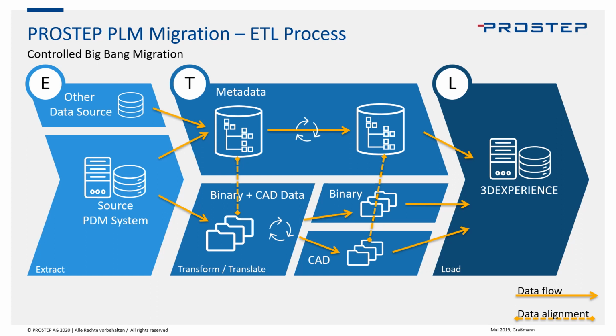Generally, CAD data with the PLM, when it's opened up, does some introspection, and then you can resolve other dependencies that are only really known in the file and not within the PLM database itself, so that all the dependencies can be loaded, and you kind of dynamically load those dependencies and save them out. Without that, you might miss files that are associated with it. You might also miss renaming of the data, things like that.